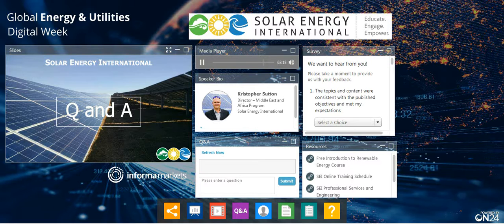Now, with that sort of system, if we're assuming that the utility has no interconnection plan and that you're probably going to have a utility that comes on and offline a lot, then having a battery-based PV system at home that can also use the utility grid to charge the batteries is a good option. Then we have a kind of full backup and we can run as much solar as possible, but not export to the grid. Okay.